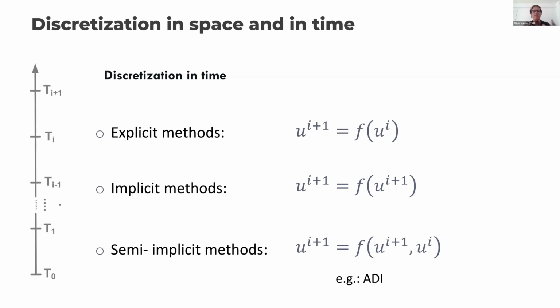So this is always a compromise. We are always trying to increase the delta t as much as possible. But because in both the explicit and the semi-implicit cases some of the neighbors are from the old time step, we cannot increase the delta t that much, okay?